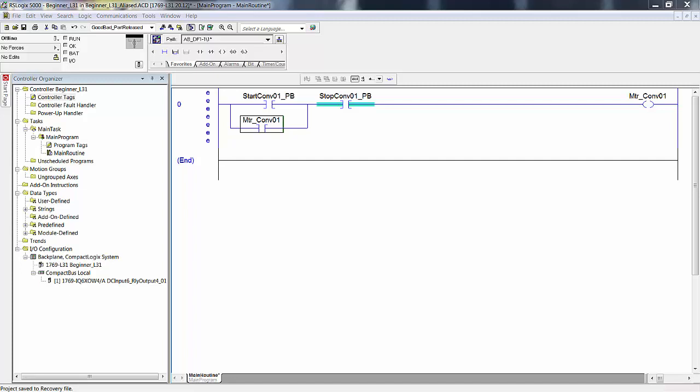This feature, concurrent engineering, also allows you to discover additionally needed I/O devices that would not be apparent until the program is written and you discover that you do not have the device on the I/O sheets of the drawing set.